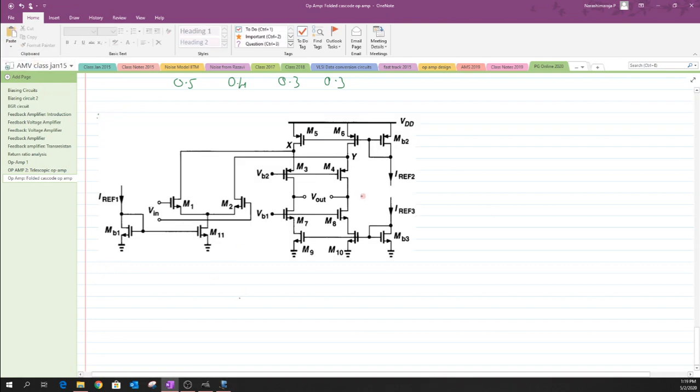So in this case, we found that there is a common mode voltage which we have yet to identify, and the total output swing away from this common mode voltage is supposed to be 0.75, because we have to have a total swing of 1.5 volt, and it goes down all the way from this common mode voltage by a value which is again 0.75. Now we know that this voltage is supposed to be equal to VDD minus the VOVs of M5 as well as M3.